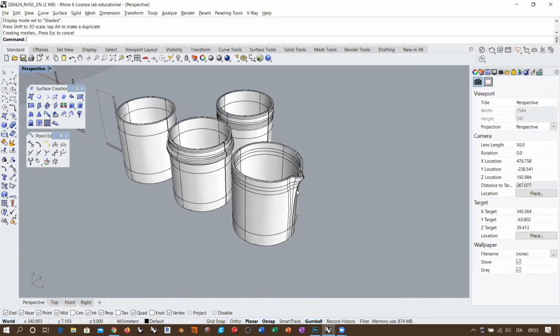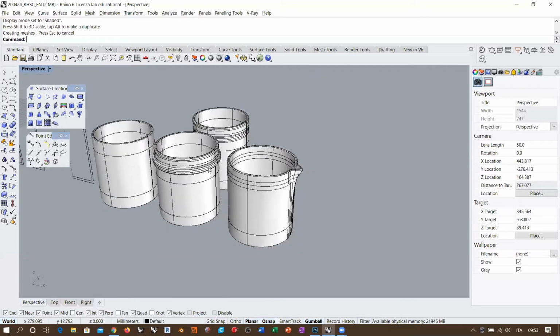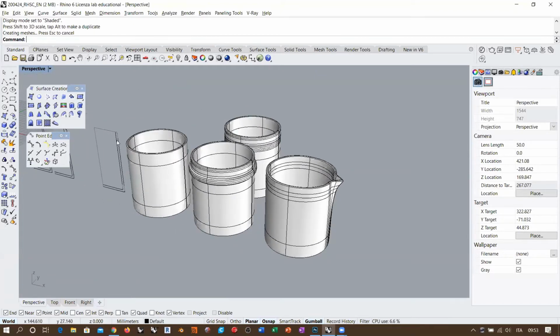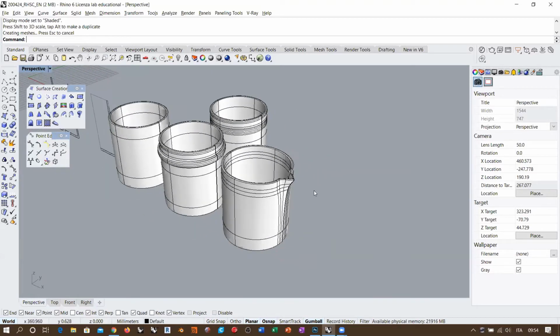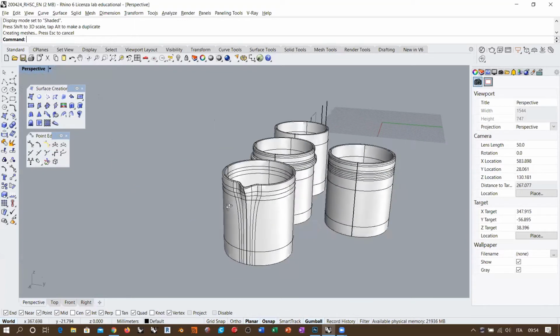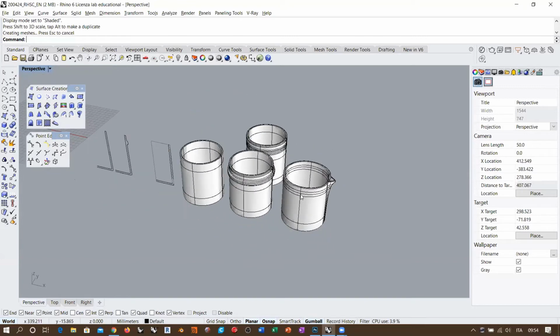So if we want some local deformability, we cannot work with the initial topology, because we will always miss the correspondent longitudinal necessary topology, because this will always be based on the circle rule, okay? But if we want the local deformability, you have to make some topological editing after creating the surface, which, by the way, means creating either knot lines or control point lines or kink lines as well, if you want to create some creases along the path, along the surface, okay? And then there is the last.